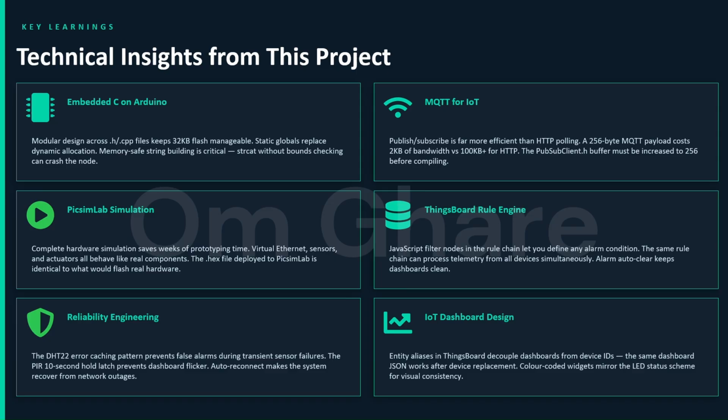Now, the key learning of this internship: I got to know about Arduino embedded C, file management and how it is done, how we can store the files in more formats, then the PicsimLab simulation using the sensors and actuators, deploying the .hex file from the Arduino to the PicsimLab, then reliability engineering, that is, sensor data with a caching pattern to prevent false alarms, and a 10 second hold latch to prevent the dashboard from flickering.